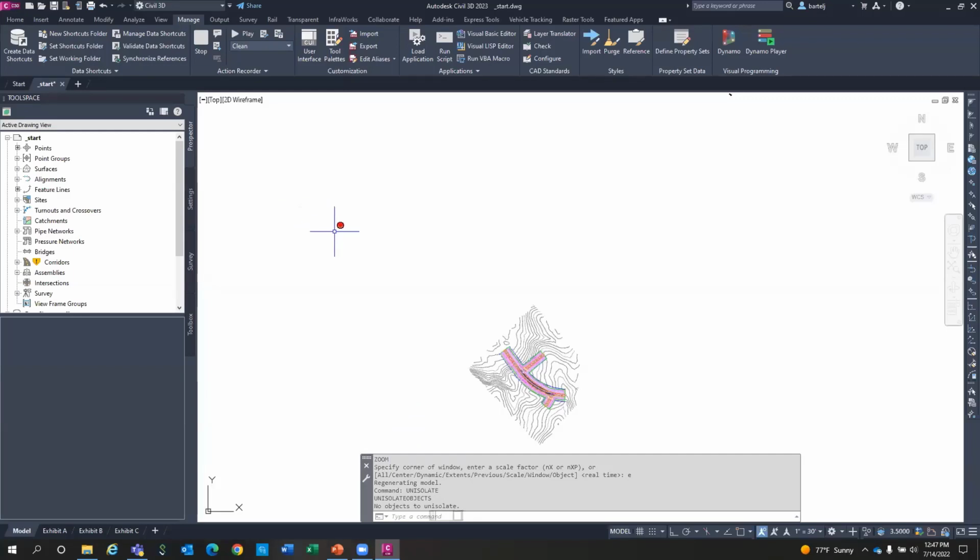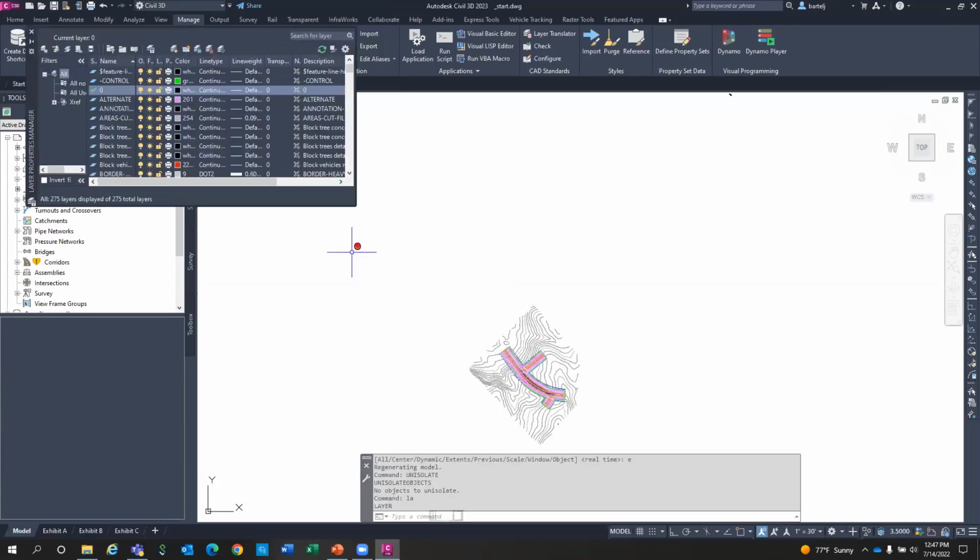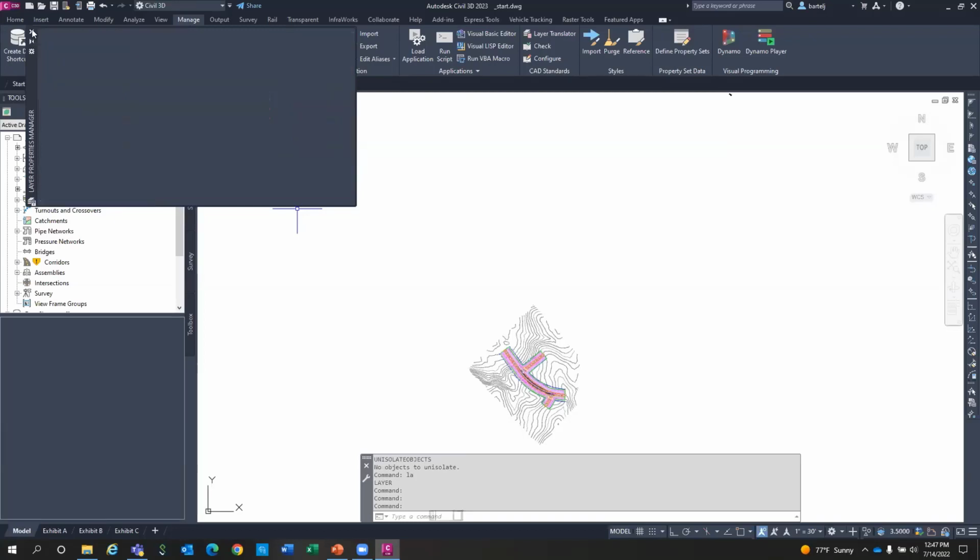As I mentioned, dialog boxes, you can't drive things in the dialog boxes. However, there are some instances like in the layer dialog box and maybe in the design center, properties. There are some things you can do in those dialog boxes. For example, I'm going to create a layer. I'm going to use the dialog box as part of my macro because it's still running. I'm going to build a new layer here and I'm going to call it Jerry. And we'll set it to current. All right, and we'll close out of that.